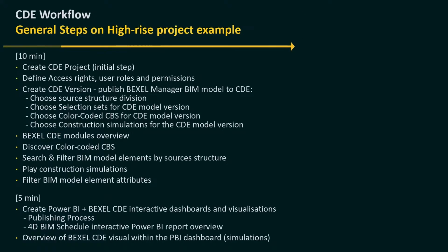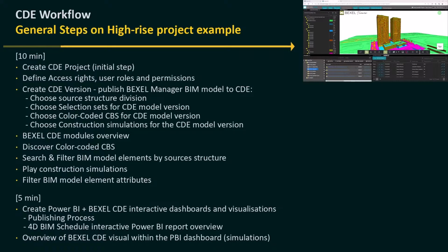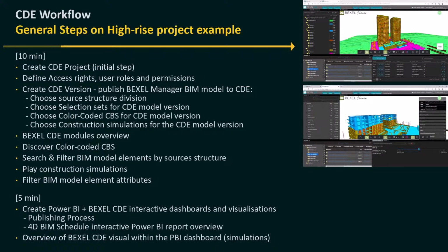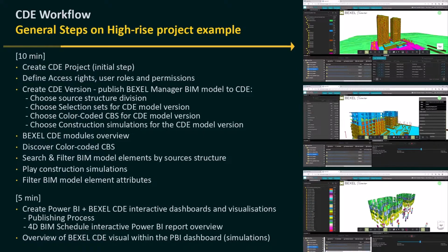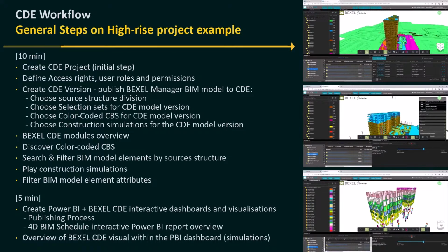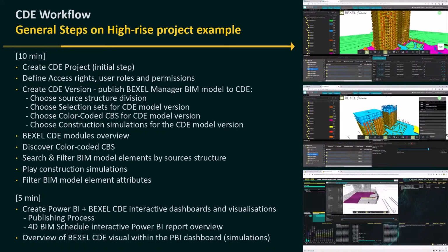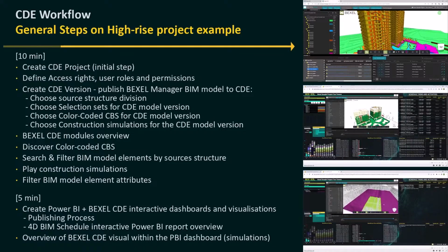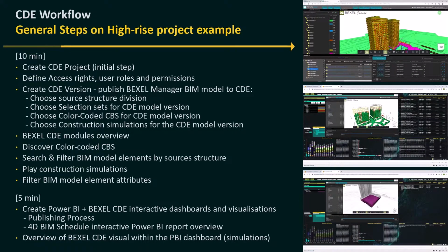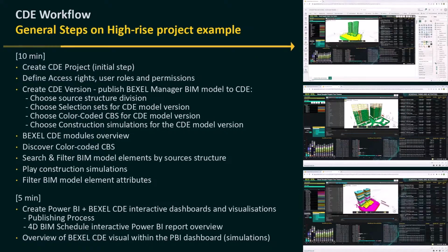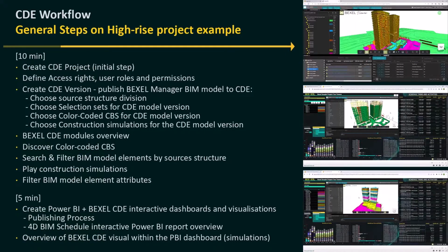Once the schedule is created within BEXEL Manager, this workflow can be extended within our cloud-based solutions, and it includes the following steps: creating a common data environment project, defining access rights, user roles and permissions, creating common data environment project versions, BEXEL common data environment modules overview, discovering color-coded custom breakdowns, search and filter BIM model elements by sources structure, construction simulation overview, filtering BIM model element attributes, and finally, creating Power BI interactive dashboards and visualizations and an overview of the BEXEL common data environment visual within the Power BI dashboard.